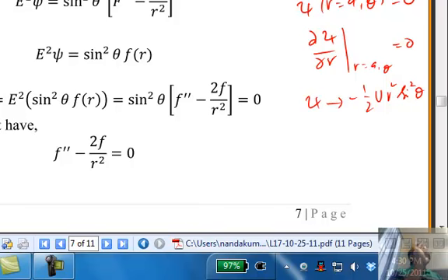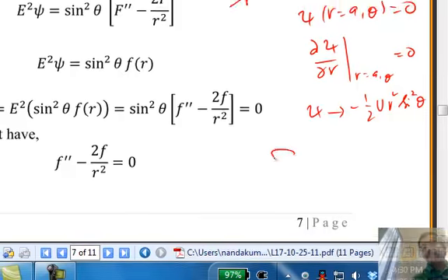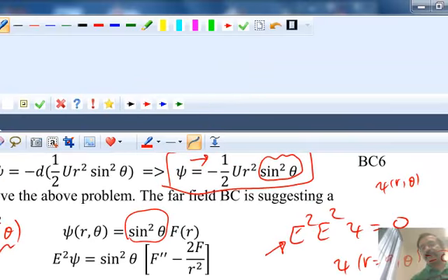That is valid only for a sphere. If I put a cube there, that will fail. Okay? Let me ask you this question. Instead of a sphere, if I put a stone with a very arbitrary rough shape, will the equation change? The equation is the same. It's basically the Stokes equation outside of the solid shape. So I could have a rough object like this, and the fluid is flowing past it. The drag exerted on that will be different. Okay? And the governing equation is the same.